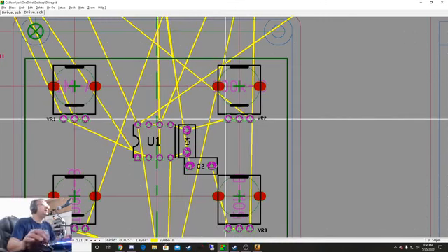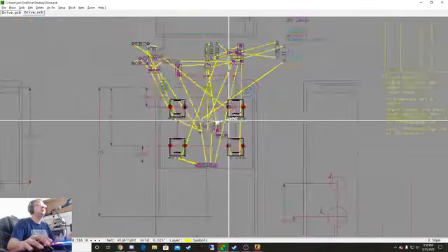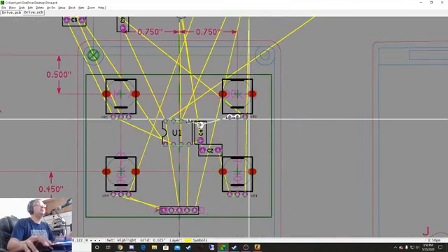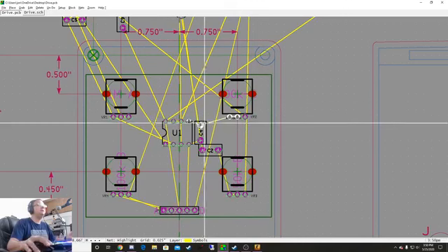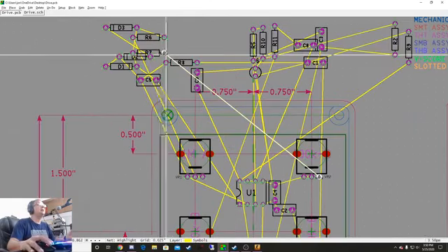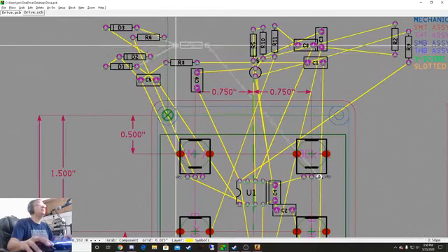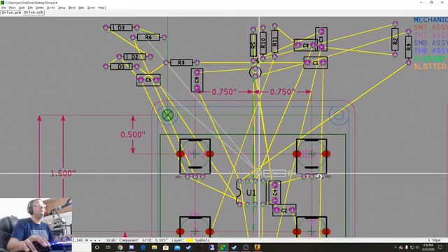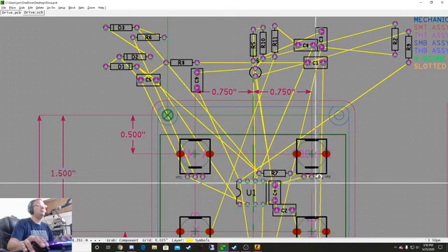Now, if I want to see where things are connected to give me a good idea of where I might want parts, then I hit NH for net highlight. So I'm going to go over here, NH. So you'll see all of that stuff turned white, so there's nothing else going to that node. So let's go to the next node, or I got this part right here. So this part's going to connect there somewhere, so I have no idea where I want it, but I'm just going to randomly put it there.